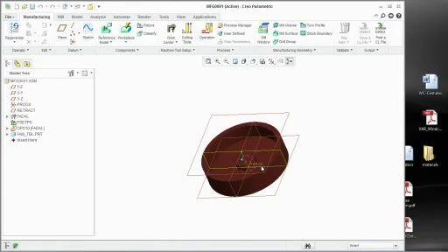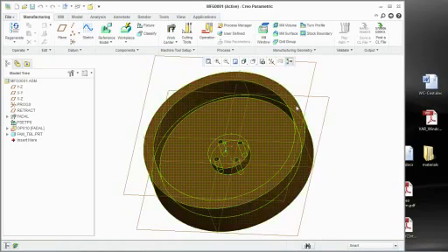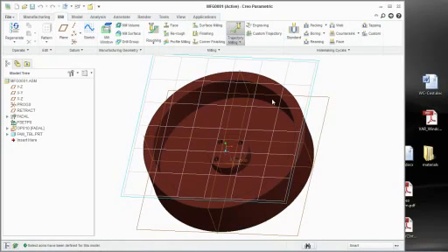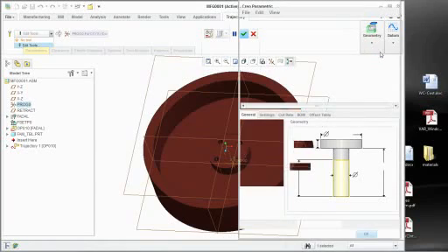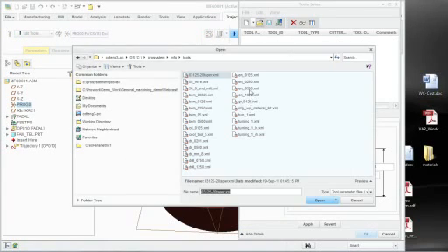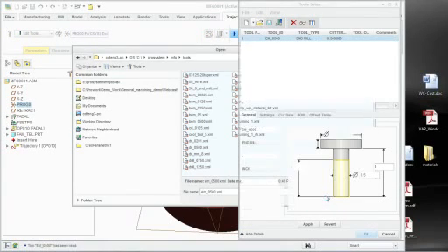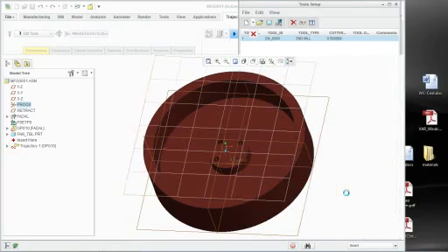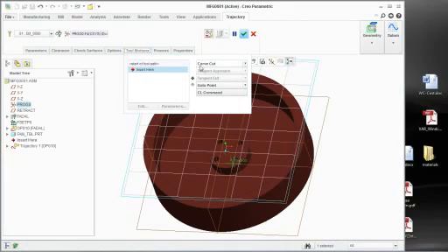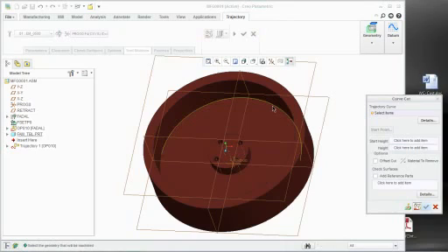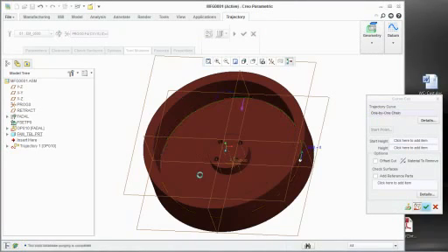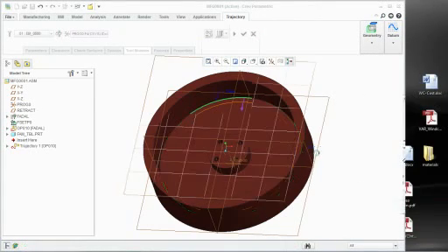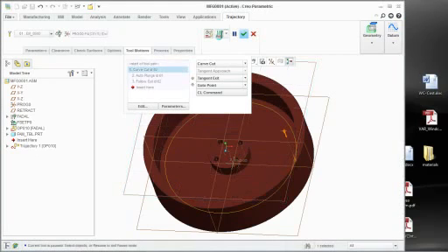I'll create here a quick toolpath. We'll just create a quick trajectory. We'll use the flat half-inch end mill. There it is. Pick our tool motions that we want. We want to follow this guy and that guy. We do want to offset it. We'll offset it to the inside. So a pretty straightforward little toolpath that I have.